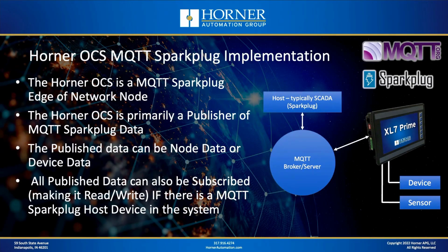So let's say you've got a set point for the level of a well that you're controlling with an OCS, and you want that system to be reporting on MQTT. Well, the OCS is going to be reporting things like what is the well level, et cetera, but another piece of data that it's going to be sharing is what's my current set point for the well, maybe 10 feet, 9 feet, whatever the case may be.